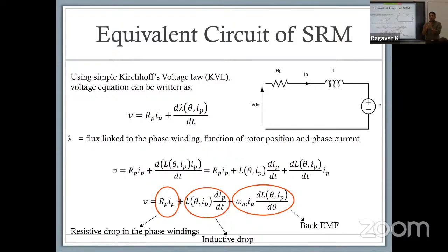So what we remember here is that my back EMF is a function only of the field component. My torque is a function of both field and armature. So the idea was change the armature, you can change the torque, change the field, you will affect both, right? So how you apply current is what we try to do also when we talk about vector control, field orientation control. We went from there.